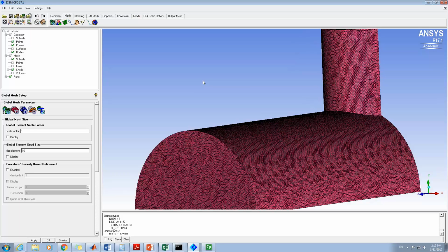Of course, more mesh control volumes also implies longer CFD simulation time, right? It means you have to spend longer time and more computer resources to do your simulation. So that is why a structured mesh is also desirable in many cases.